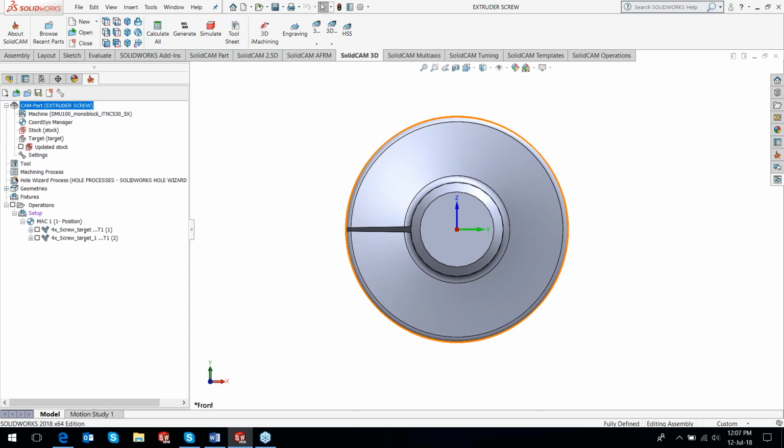So it simply keeps offsetting the inside or the outside cylinder till it meets the inside cylinder, and at each offset, which is defined as a depth of cut by the user, it will create a slice, and these will be cylindrical slices. And in the end, it will just create a morphing kind of toolpath between those slices that it has generated to create a roughing toolpath.